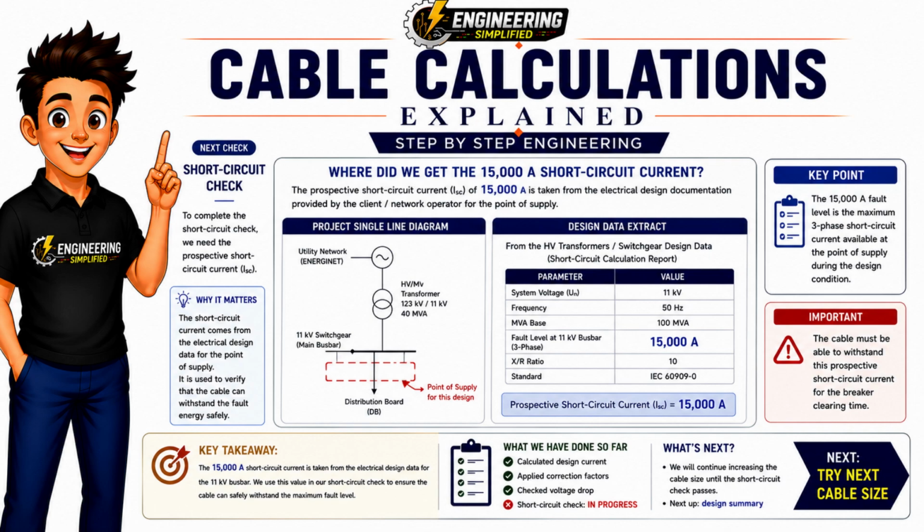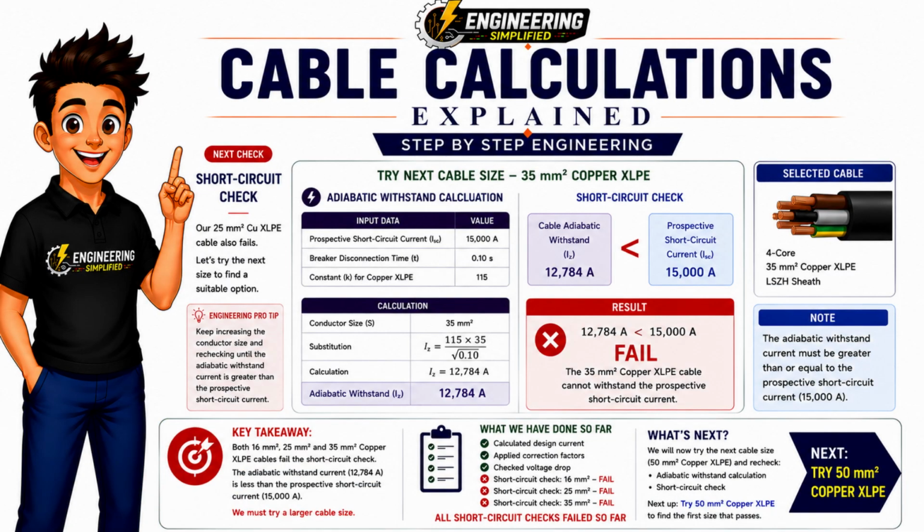This is the value we must use when checking that the cable can survive a fault until the breaker disconnects the supply. Always remember, the cable must be designed for the worst fault that could occur at its point of installation. Next, let's try a 35 square millimeter copper XLPE cable.